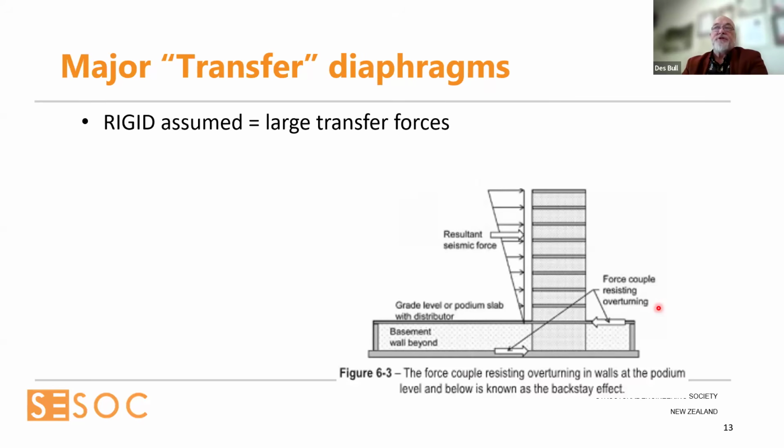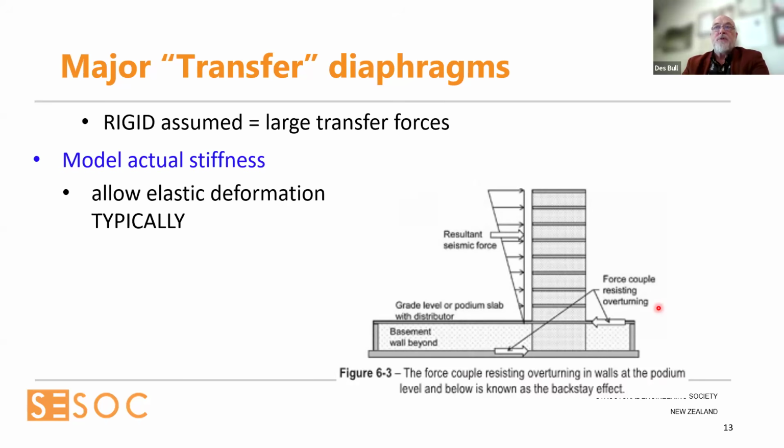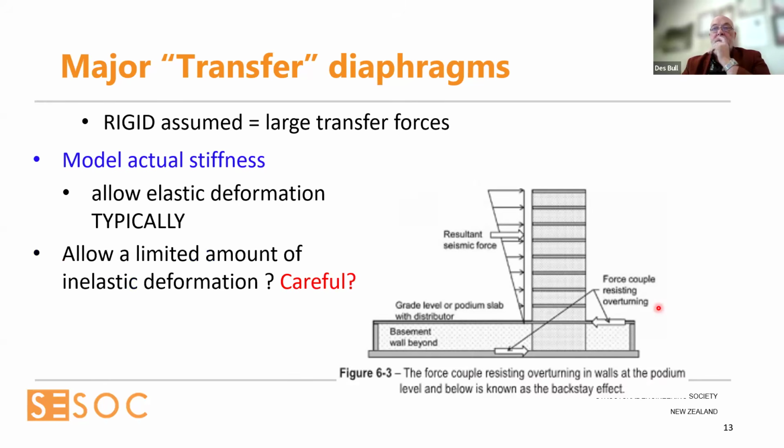If rigid diaphragms are assumed, you will get very large transfer forces. And it doesn't take much actual modelling of the stiffness, allowing for some actual elastic deformations in the system. I'll come back to that. Try and allow for some actual elastic deformation in the diaphragm. That will significantly reduce the transfer forces.